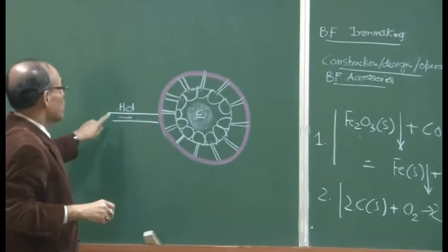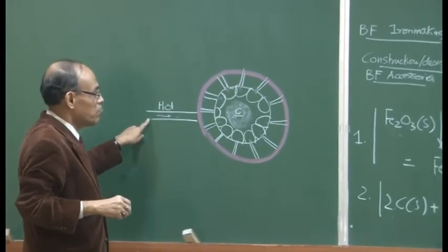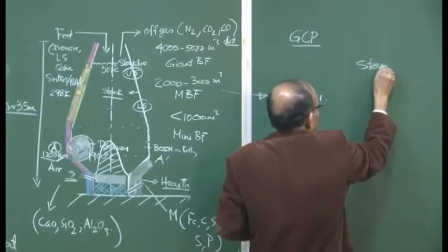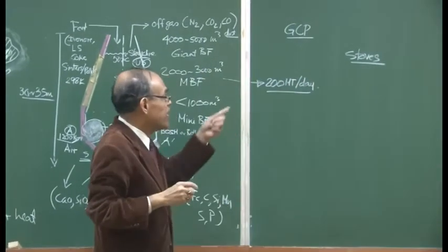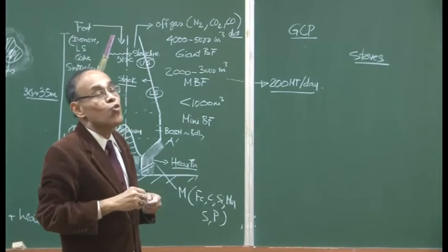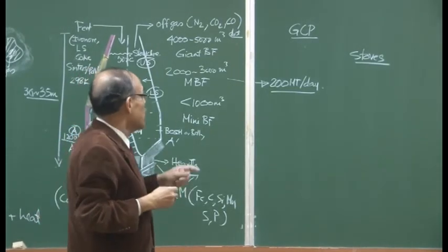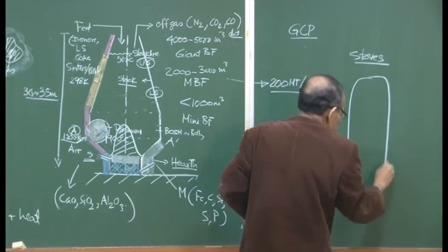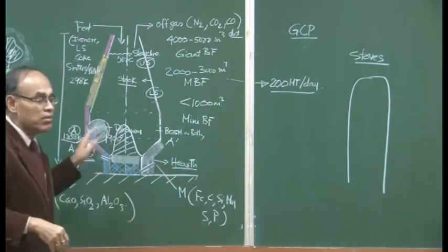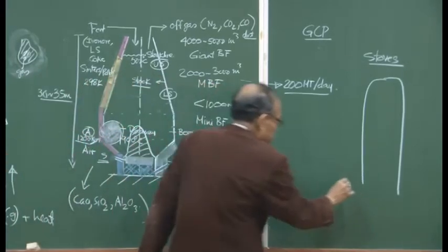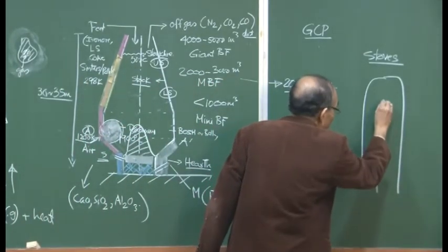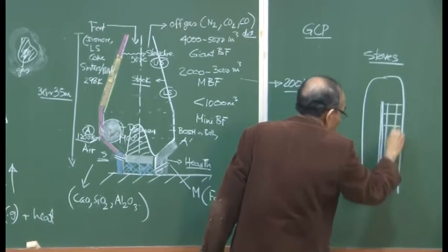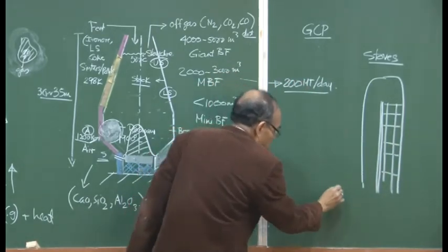let us look at this satellite, which is the supply of the preheated gas, and these are called blast furnace stoves. There could be 1, 2 or 3 stoves per furnace. The blast furnace stoves are tall dome shaped structures. You cannot miss it. It is possibly as tall as the blast furnace itself, and we will understand why it is so tall. This has 2 different compartments. One compartment, again the drawing is there in all textbooks, or you can find it online. It has a brick checker work here. This is the bottom.